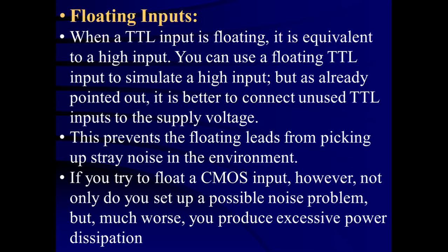In this, the first characteristic which we are going to study is the floating input. In TTL also we have studied about the floating input. What does floating input mean? For a TTL gate, or here a CMOS gate, if there are a number of inputs and some of the inputs are unused, which are not required, then that input can be kept floating.